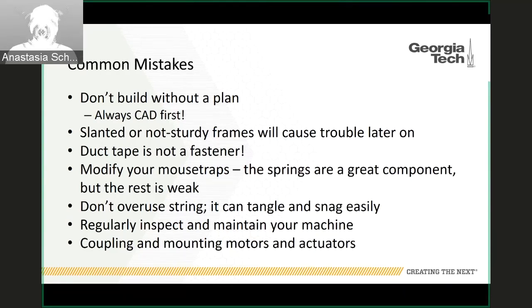So as I said earlier, you should always make a CAD model first. When you're putting together your frame, sometimes they end up slanted or just not very sturdy. Your right angles are really not right angles. That may end up causing you trouble later on, especially as you start mounting things to the frame and adding more components. So it's always good to fix that up front. Remember that duct tape is not a fastener, and neither is hot glue, really. We don't ever want to see any duct tape or hot glue at design review.